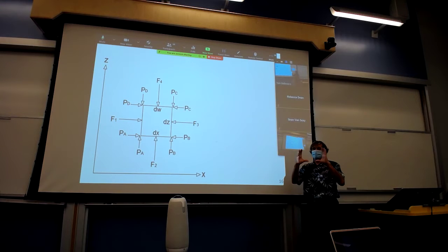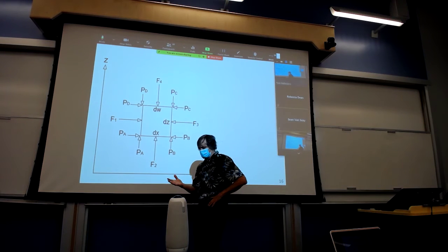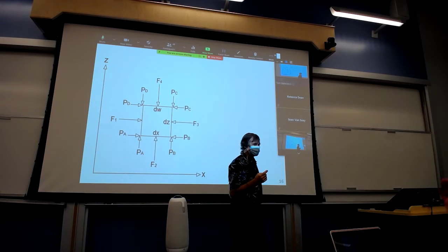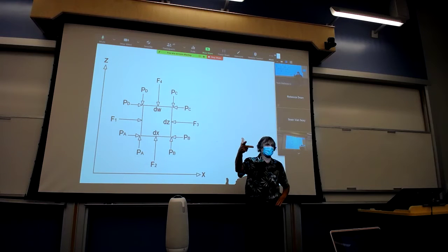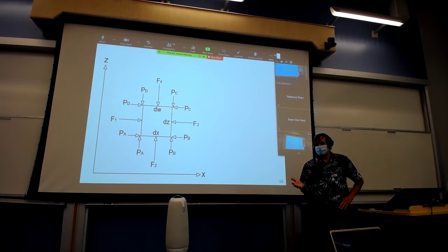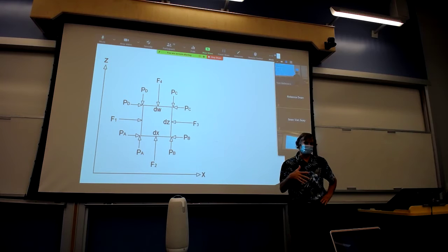So we started with a differential cube of a fluid, completely submerged. And then instead of a three-dimensional analysis, we looked at a two-dimensional analysis. The reason for doing that is that we oriented our XYZ axes such that the Z-axis was collinear with gravity. Therefore, X and Y have no other external forces or accelerations acting in them. So if we do a two-dimensional analysis, whatever we find for the X should be true for the Y.